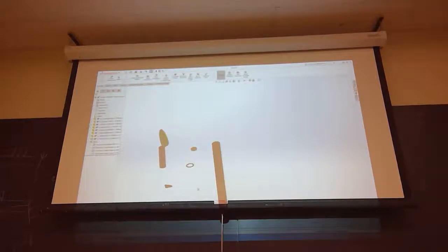Oh, okay. So what you did is you fixed both. Yeah, there's a measure. I think it's 30 inches. Okay, so you don't want to fix both of them. Go to evaluate. When you fix two, that's a constraint, and you're trying to have two things that are fixed and then move them together. That's contradicting, right? So go ahead, hit this. He just wanted to see what the dimension was. Boom. There you go.